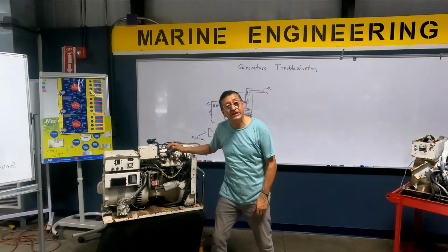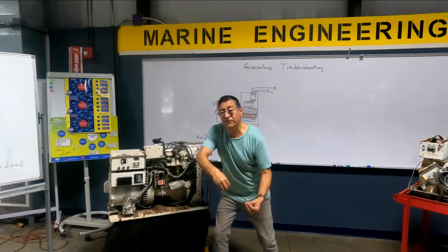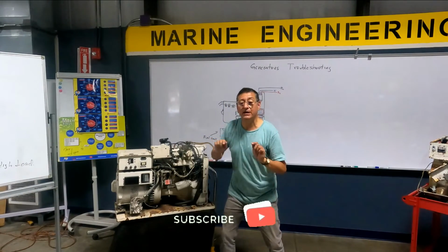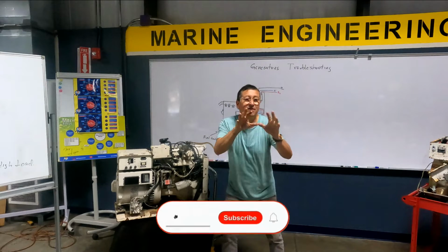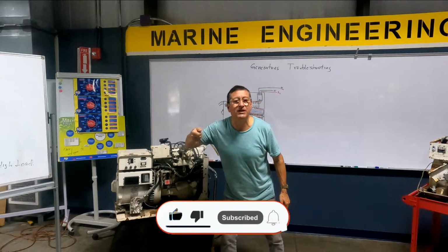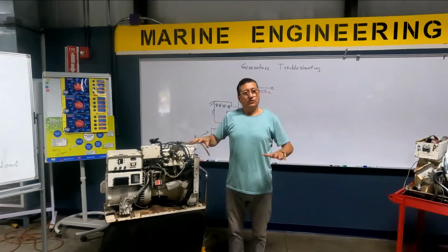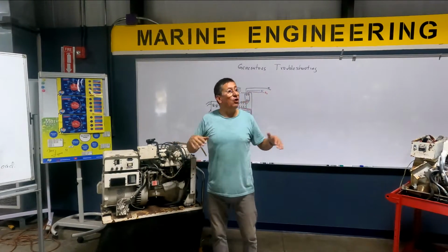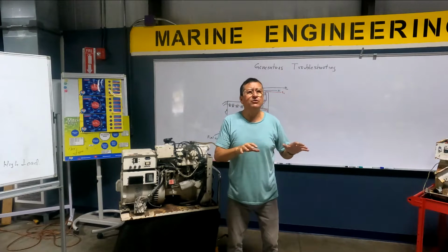If the engine is fuel injected, the low pressure pump or transfer pump brings the fuel from the fuel tank into the high pressure pump to the injectors. Now, this is the function of the preheat. And you hear that pump when you activate preheat or ignition position. You remember that? Yeah, this is DC. All of those elements, the fuel transfer pump, the solenoid, all of those are DC.